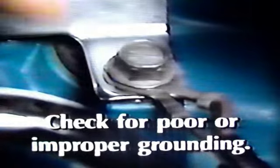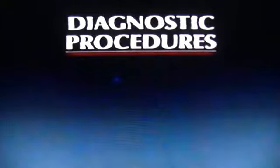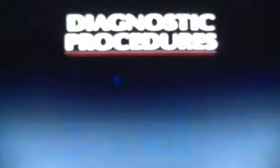Another thing to look for in your visual check is poor or improper grounding. There may be 3 or 4 ground wires, all terminating in a bolt, screw, or lug in the engine compartment, and they can get loosened or damaged or corroded over time. So check to be sure the system is properly grounded. Having completed the visual check steps, we can now turn our attention to the actual diagnostic procedures.